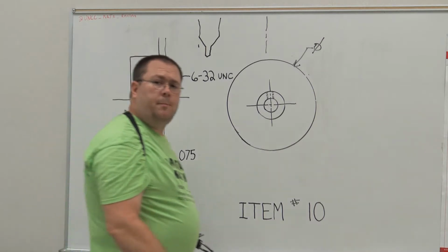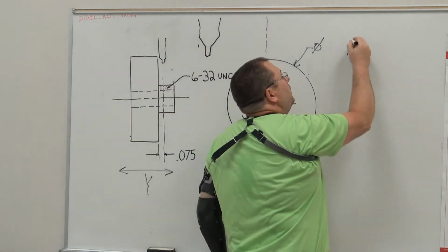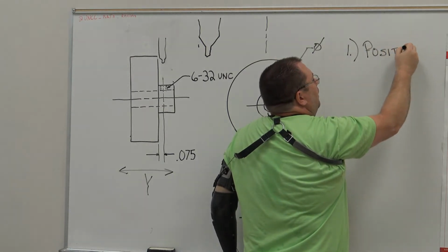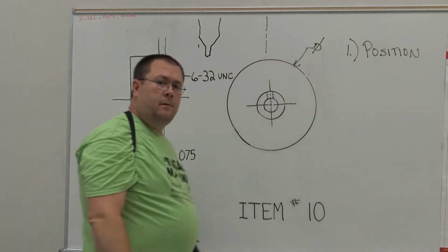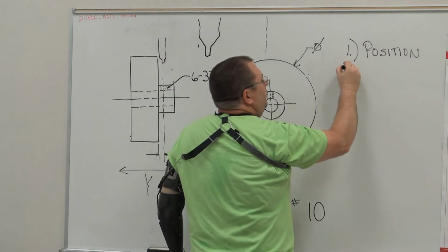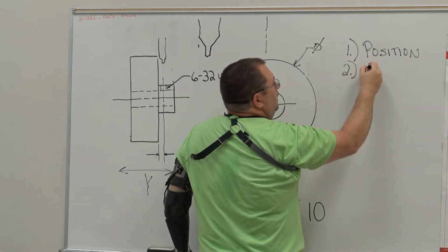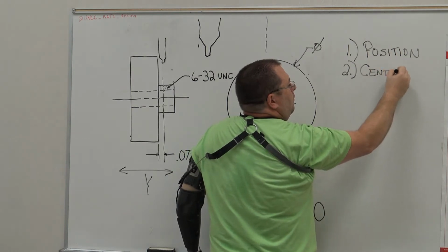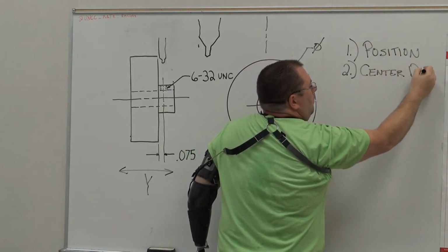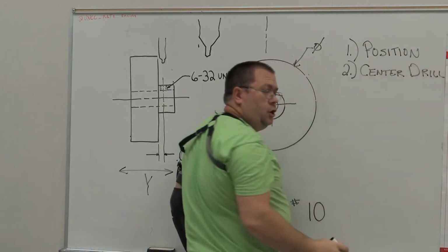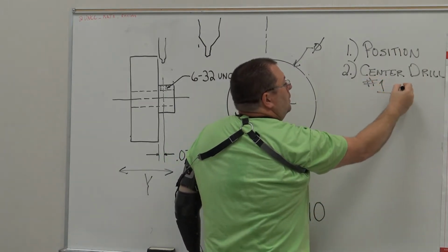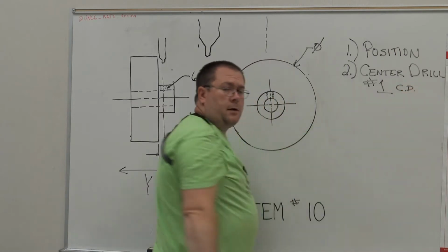So once we do our positioning, so number 1, position, okay? Number 2 step is going to be center drill, using a number 1 center drill.